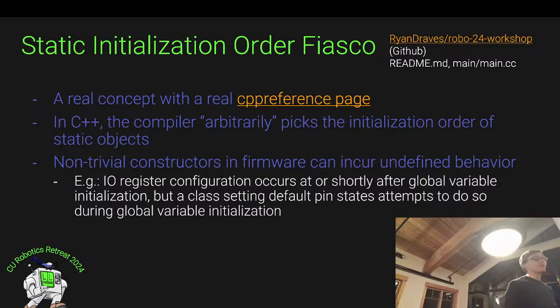And typically for embedded systems, what you're compiling for is memory. Very typically, you're going to run out of memory, so instead of the speed of the program, you're going to say, make sure that this program fits into as small of a footprint as possible so I can upload it onto the flash. And when you do this, the compiler will say, okay, I'll do whatever it takes. And whatever it takes sometimes means taking global variables and rearranging the order at which they're initialized. So when you have global variables, they get initialized before you enter your int main function at the start of the program. And this random ordering can get you into a lot of trouble.